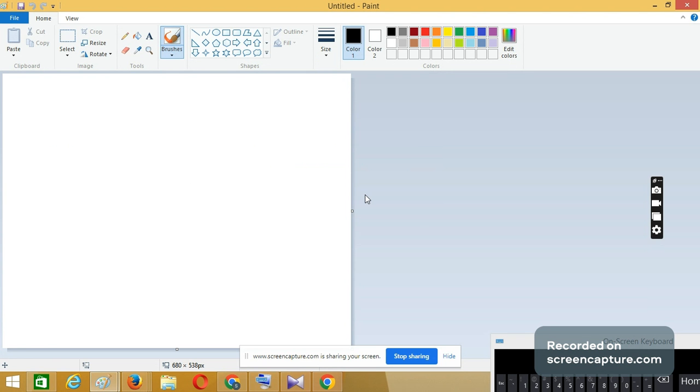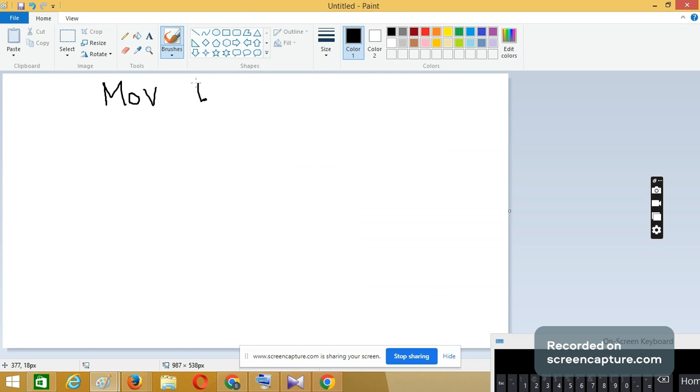So let us start the program. You remember the connections. Wherever we have connected, you have to remember. First, the P1 port is expected to carry the digital data coming through D0 to D7. That means P1 is an input port. So you have to configure P1 as an input port. How will you make P1 an input port? You have to give FF to it. So this declares P1 as an input port.